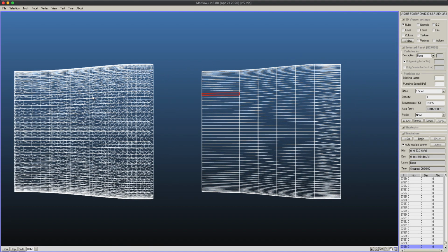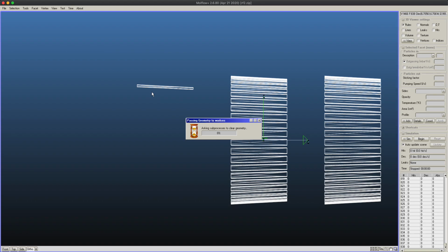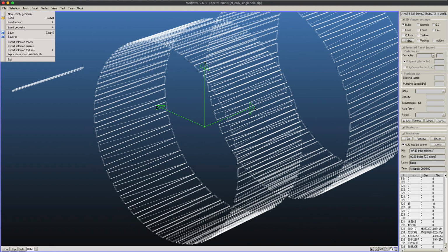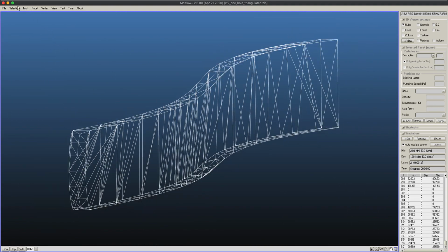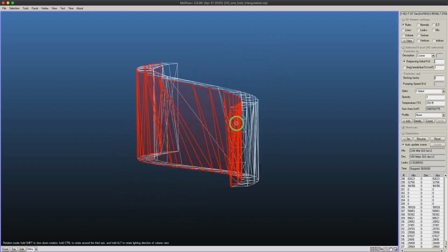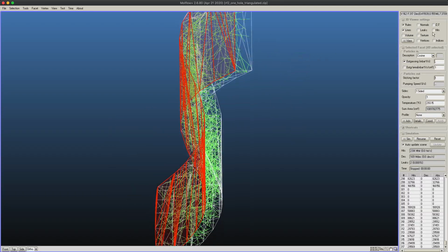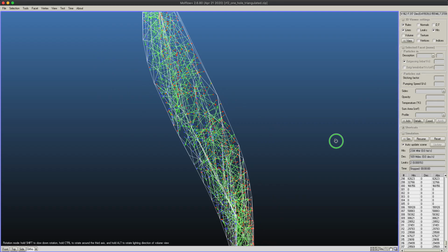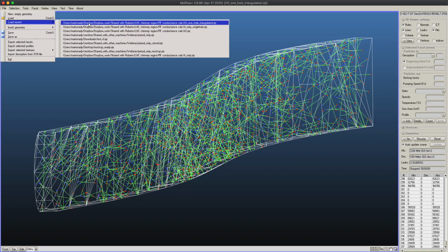Here I was calculating the area ratio, and then I was doing the simulation of one single hole. And here, one single hole, when I select this option, I cannot modify the geometry, I have to use the triangulation command. So this is what will be available in the next version. If I turn on the lines, you can see that the simulation is just like before. So I'm desorbing from one side and the other is sticking, so I can still calculate the transmission probability in this irregular shaped wall.